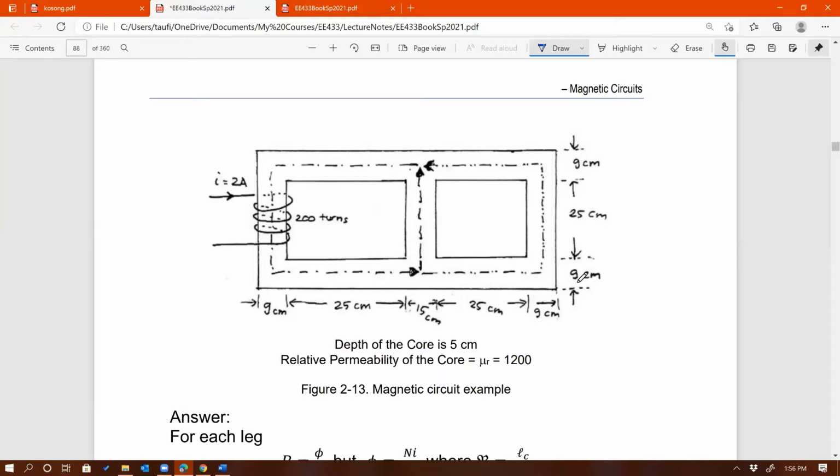The left. Why is that? Is it the source of the other flux? Yes, because it is the MMF. This is the one that produces the flux that would then split. But you have to be careful as well that flux density is a function of A. So when it comes to flux, I should probably ask more specifically about flux. But for this one, yeah, left should be the highest.